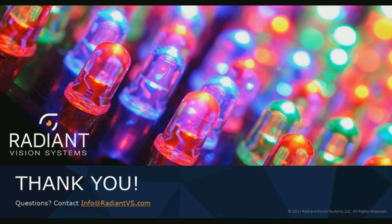And this person asked, can your system be used to measure ultraviolet or infrared sources? That's a great question. The sensors within the cameras have a sensitivity range of about 350 nanometers to about 1050 nanometers. So outside of that, not really. Inside of that, at the ends of the spectrum, the sensitivity does fall off and become less and less sensitive towards those edges. But yes, it can be used to measure those wavelengths respectively.